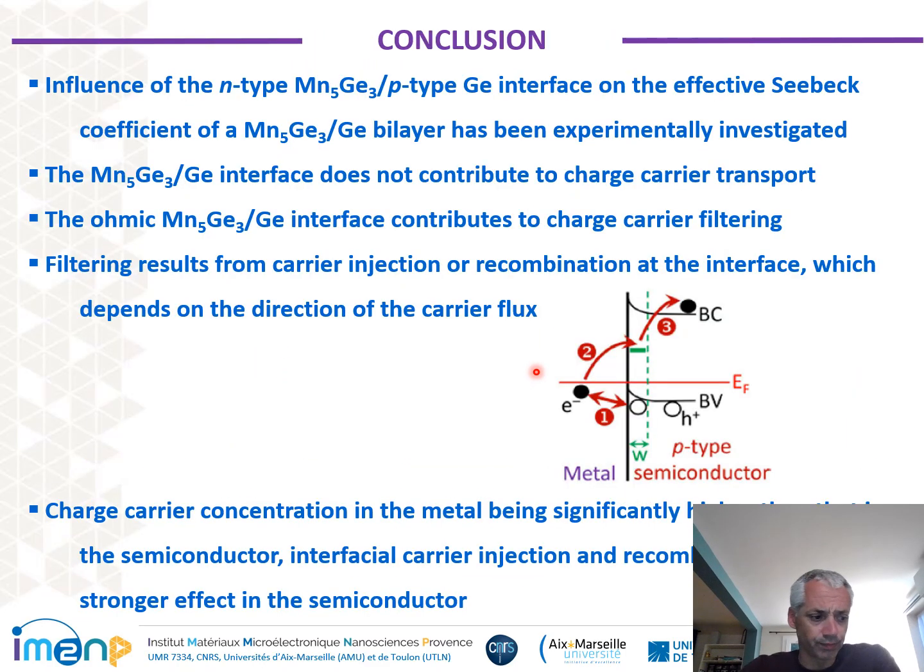So in conclusion, we investigated the influence of the interface between an N-type Mn5Ge3 film and a P-type germanium film experimentally. We showed that the Mn5Ge3 germanium interface does not contribute to charge carrier transport, but this interface is ohmic and contributes to charge carrier filtering.